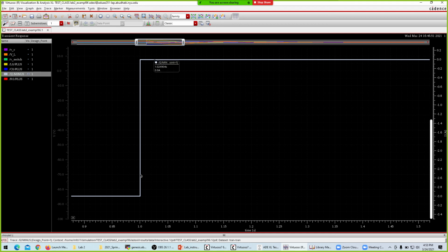When we are looking at this plot, if we see that this area has been grayed, then you know that you have to look at the current. So here's the highlighted area. That's how you would know which area you will be looking at. All right. So the current source we set was 3 amperes before the time, and then at time 1 second it turned to 0, which is here.